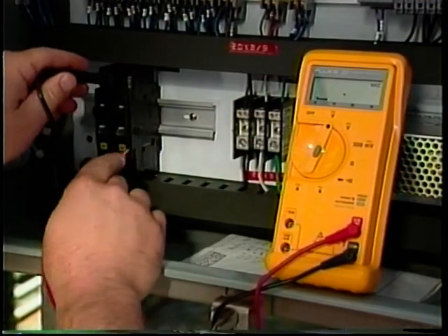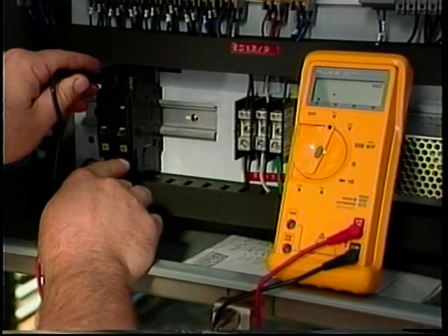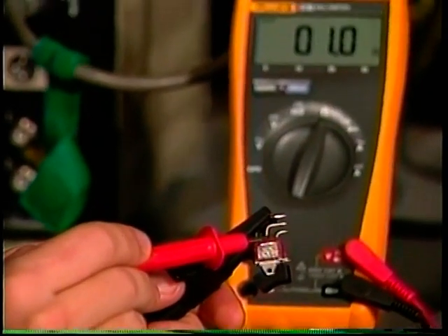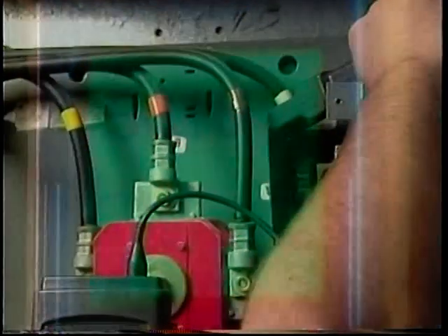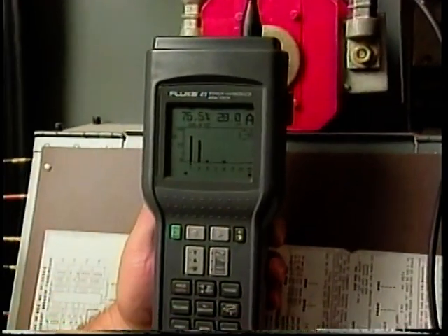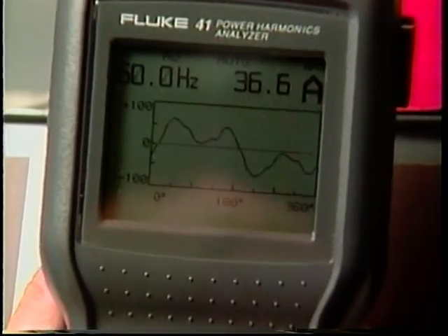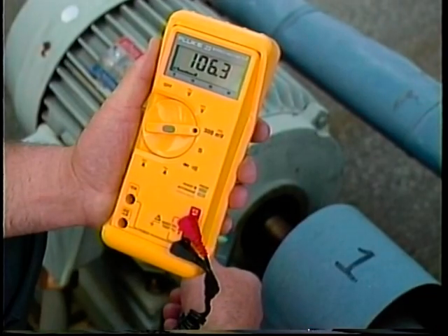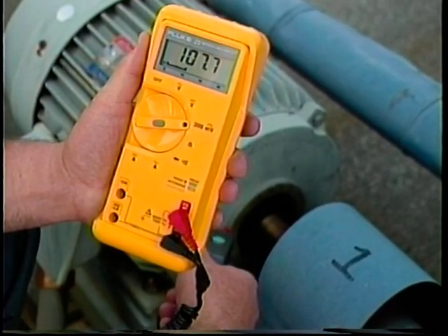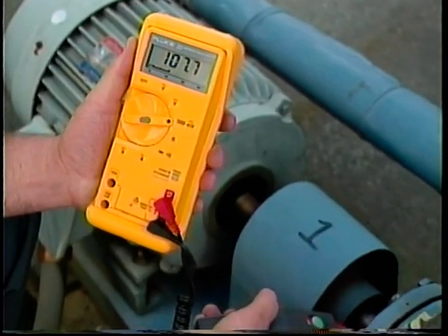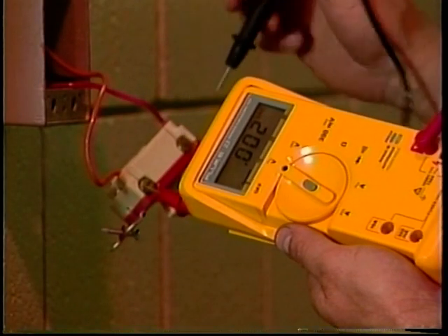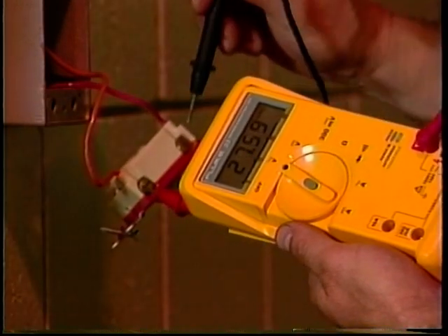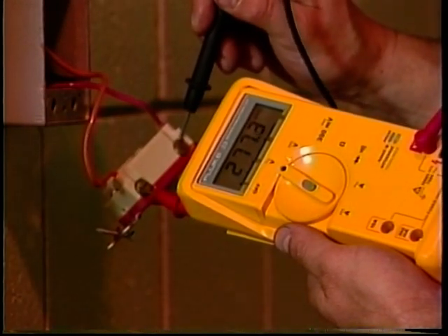DMMs are selected for specific applications. Standard DMMs are used for basic voltage, current, and resistance measurements. High-performance DMMs are used for troubleshooting more complex problems, such as improper frequencies or momentary problems. DMM accessories are used for special applications, such as measuring temperature. For maximum safety and efficiency, a technician must be familiar with fundamental DMM operating procedures.